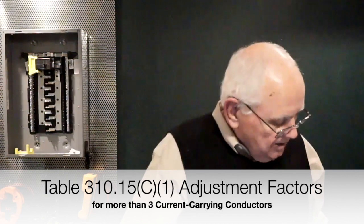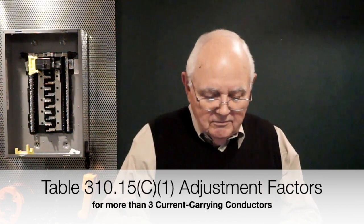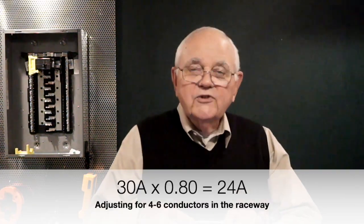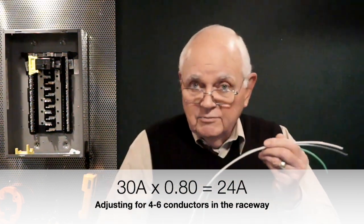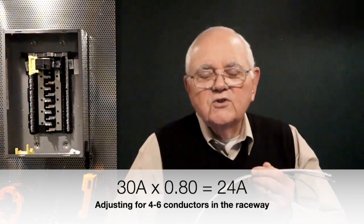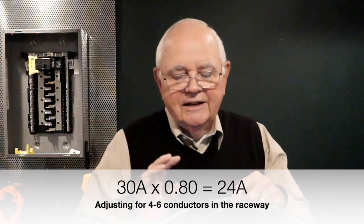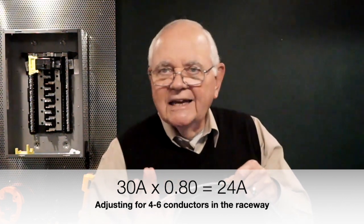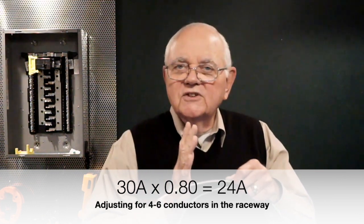And it tells me, for instance, if I have 4 to 6 conductors in a raceway, I have to reduce the ampacity by 20%, or in other words, multiply that 30 amps that I had for these conductors by 0.8, 80%. And so 0.8 times 30 would give me 24 amps. So if I had more than 3 current carrying conductors in the raceway, it's going to get hotter in there. I can't allow these conductors to carry as much current flow. So even though their ampacity is 30 amps, their allowable ampacity based on the conductors in the raceway would be 24 amps.